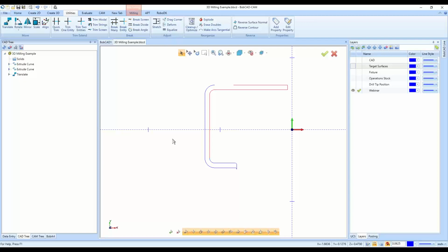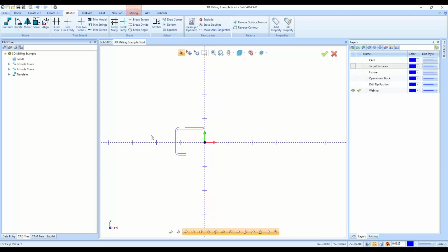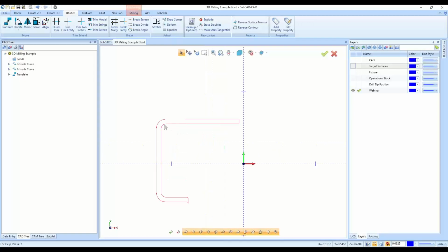This is very helpful where you're trying to create a pocket of some kind of geometry, like a slot here. If you're trying to chain select around a profile, and you think you've selected all of it, you window select it all and click OK and compute the toolpath. It's not going to work very well, or with Pocket, I don't think it will actually compute the toolpath.